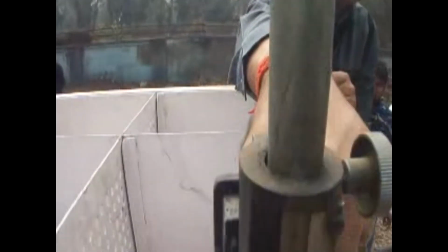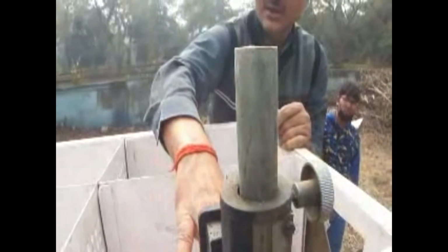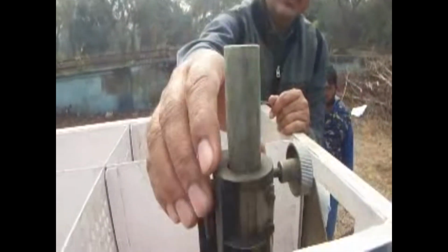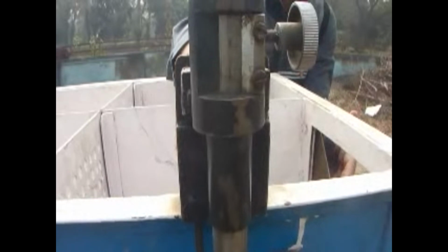Now you can see we have just here a hook gauge. There is a hook. Water is going to this basin, or stilling basin, or this compartment, which is equal to this chamber. So it is working on the principle of vernier scale. So we have main scale, then vernier scale, and we can measure precisely the head of water that is causing the flow over this crest.